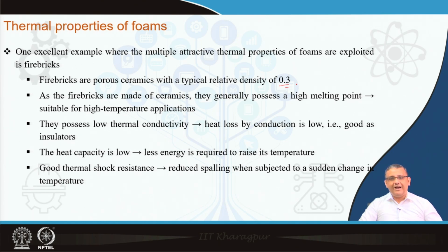And also, because fire bricks have a high amount of pores, the pores also reduce the Young's modulus of the material, and that is the reason these fire bricks also have very good thermal shock resistance, because, as you will see afterward, the thermal shock resistance of a material is a function of the Young's modulus. The higher the Young's modulus, the worse the thermal shock, because you have more thermal stress generation. Also, fire bricks have less heat capacity, which means that to raise the temperature by a certain amount, the fire bricks require less heat, which is also very attractive for furnace applications.